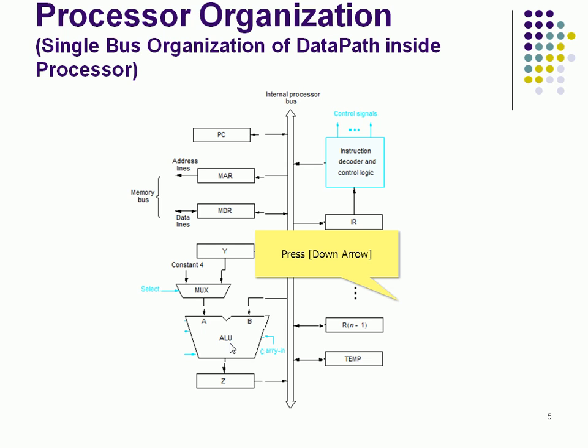processor bus. Somebody has to welcome it, whoever needs that. In the instruction itself, the destination register or destination address is specified, so that register will be eligible to receive it. If we are performing addition or subtraction, then there is a carry in and carry out. There are different types of arithmetic operations possible: add, subtract, and logical operations such as XOR. These are the ALU control lines.